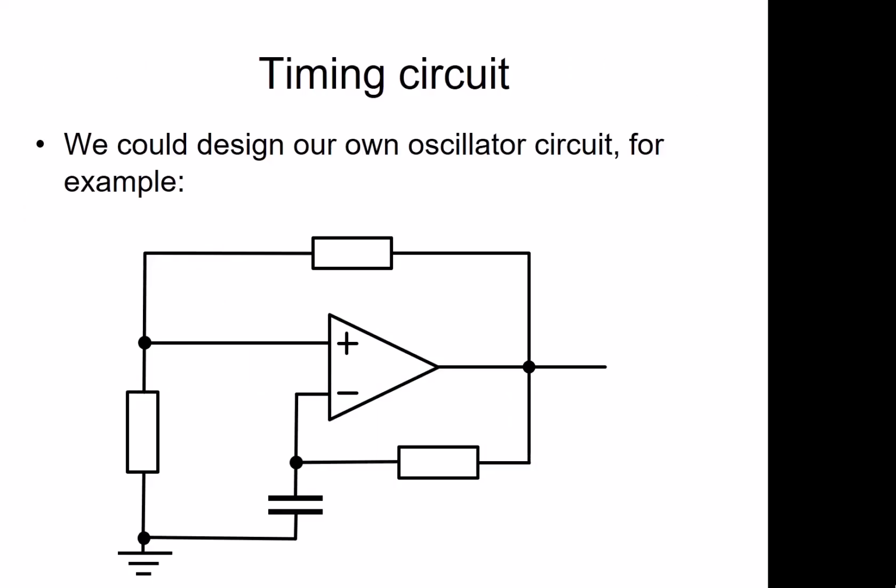This is an example of an oscillating circuit. So again, as you notice, we have got positive feedback. So the output is going to be either the plus Vs or minus Vs supply voltage. So what we'll do is we'll consider this currently as minus Vs. This is at earth, and then depending on these resistor values, this is going to be a fraction of that.